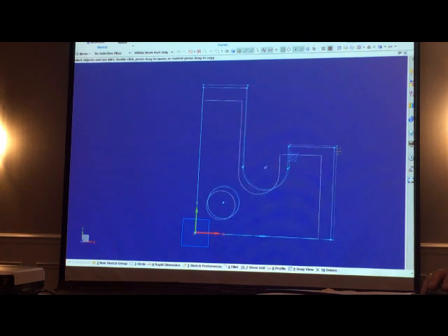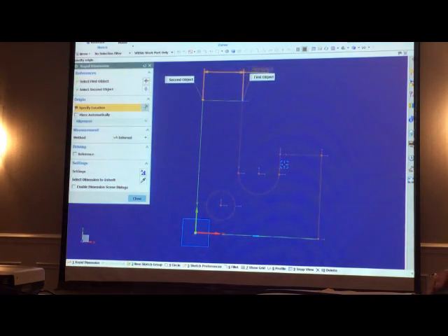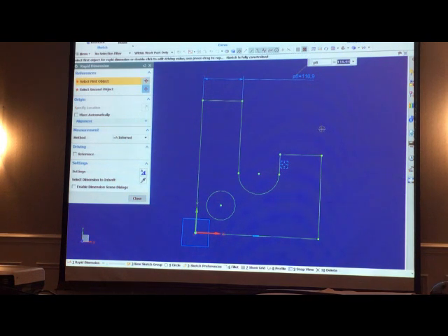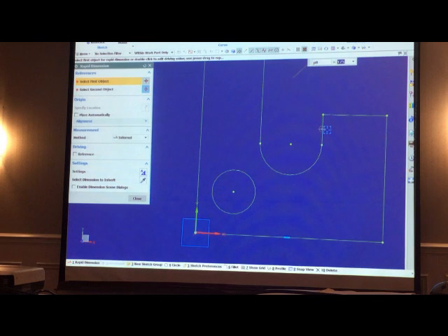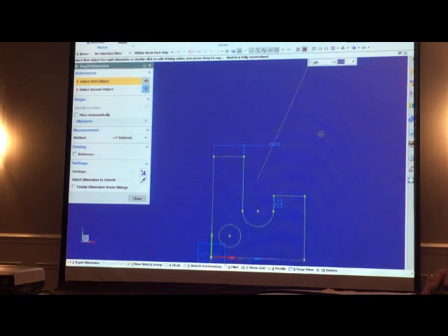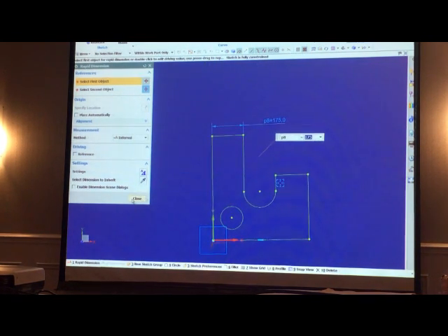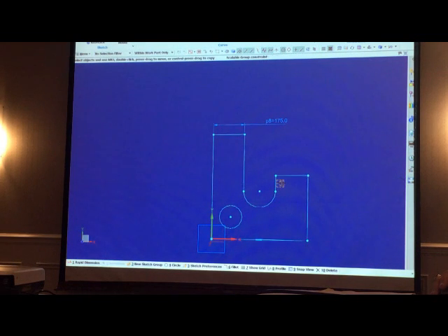So remember I said I want to make it 175% bigger? How would I go about doing that? Well, remember this dimension up here was 100. So I'm going to come here and put a new dimension, and I'm going to say 175, because now that dimension is driving the scale. Now, once I say it's 175, all I'm going to do is delete the scalable group.